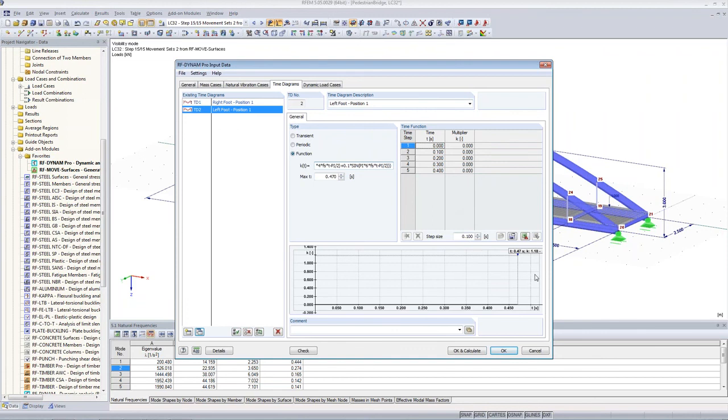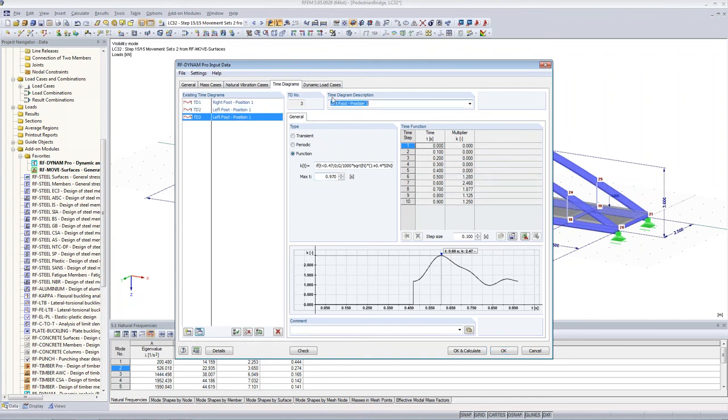And as you see nothing, because here we have a maximum time of 0.47 seconds, and I've said in my if function that it's 0 for all t's smaller than 0.47 seconds. So I have to increase the maximum t here to see something, so I end up with 0.97. So that's what I figured out in advance, obviously. So my period is 1 second because I have a step frequency of 2 Hertz. So what I'm doing now is I copy these functions and always increase by half a second if I switch from left to right foot, and by 1 second for the same foot. So this one here I have to increase by half a second because I've copied the left foot to the right foot.